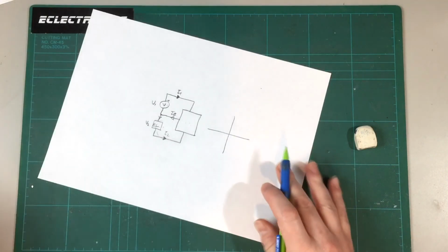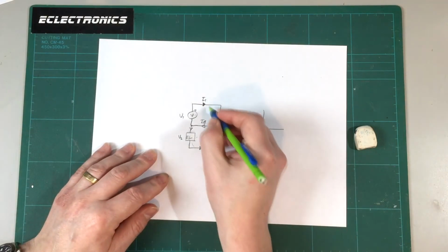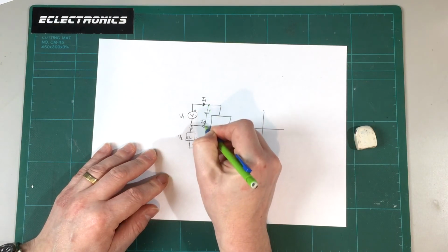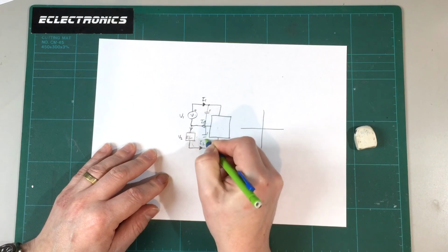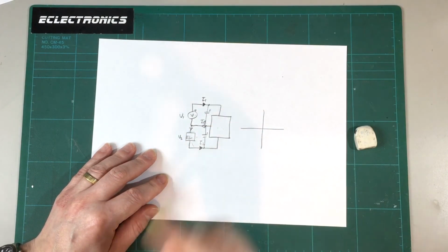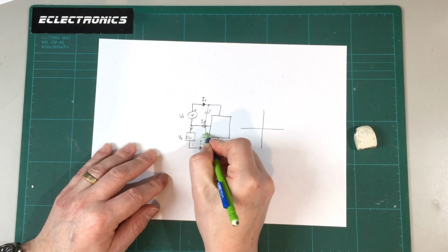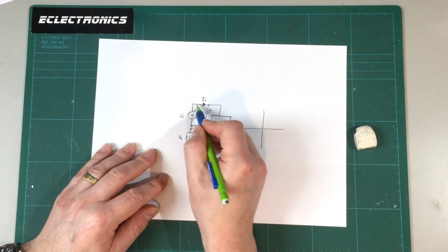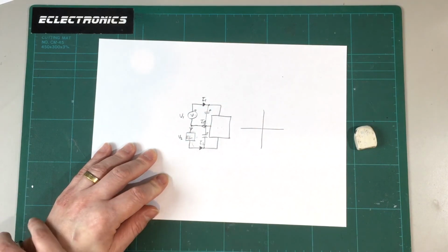So I think I'm going to have to probably add some capacitors in here just to take out the ripple and smooth things out for the power supply and the electronic load. So effectively get it back into a nice smooth DC. So any choppy currents on this side become smoother on this side.